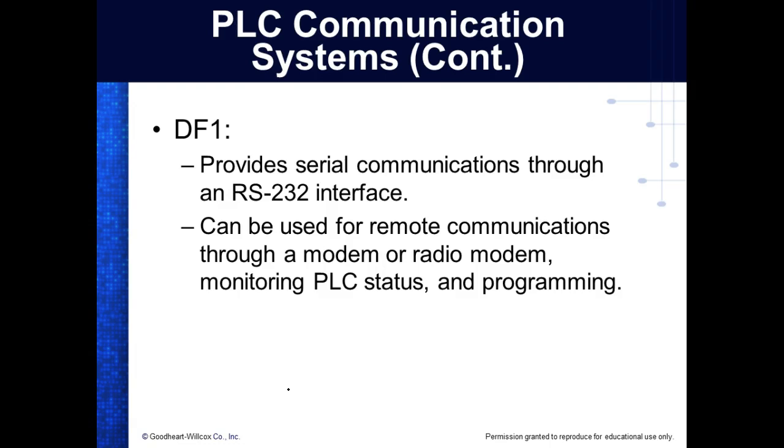Your carrier on your cable, if you have cable at the house, is sharing it not only with that. How many cables do you have coming into your house? One. How many things on that cable at the same time? Yeah, because everything's modulated, right? So what you're doing when you tune in a station is you're telling it what carrier to demodulate, and it blocks everybody else. So baseband is one device at any one time. Broadband is modulation, and you share the bandwidth on that.